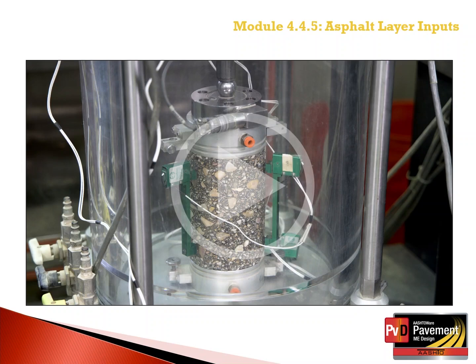The dynamic modulus option being used for testing this specimen is the unconfined condition or uniaxial type test. In other words, no membrane is used to encase the specimen. The confined test is the same as for the unconfined test, except that a membrane encapsulates the specimen.